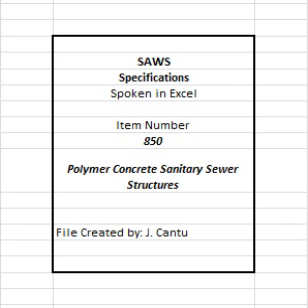11. Elastomeric gaskets shall be suitable for the service intended. All gaskets shall meet the requirement of ASTM C443. 12. Round structures shall utilize spigot and bell type joints incorporating either a confined O-ring or single step profile joint. 13. Square and rectangular structures shall utilize a shiplap joint and be sealed with a butyl rope sealant per ASTM C990 as recommended by the structure manufacturer. 14. Pipe to structure connections. Pipes shall be directly connected to all structures using resilient flexible pipe to structure connector per ASTM C923. 15. In cases where cold joint pipe stubs are shown, they shall be grouted using a corrosion-resistant grout and rubber water stop grout ring.